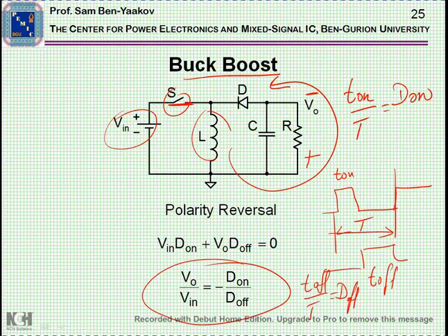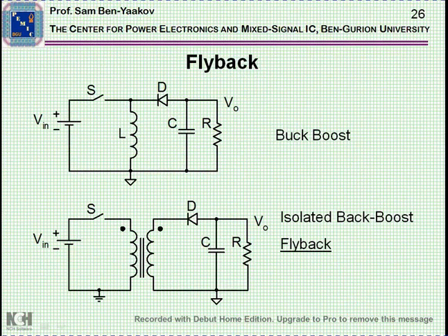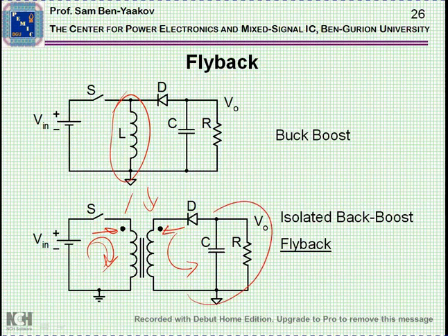Now, what we can do, instead of having one inductor, is use a magnetic element which has two windings on it. That is a coupled inductor. And as before, we'll have a primary in which we pump in energy, and then a secondary in which the energy is released out, so that when the current goes in here, it'll go this way, circulating, and we'll get a voltage like this.